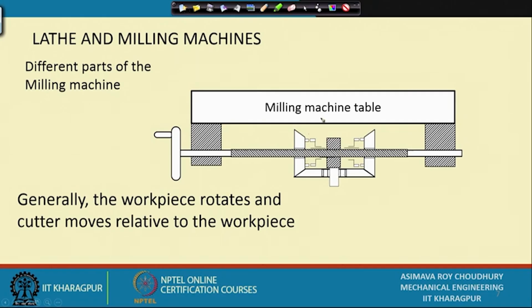I am having rotation of the table, I am having automatic motion coming to the screw, and I am having direction also selected. However, this sort of complex mechanism is not always implemented in one step itself. This clutch is taken out and made use of in a different shaft, because this sort of bidirectional clutch has to be in two parts, though generally it is in a single part. Let us quickly have a look at it.